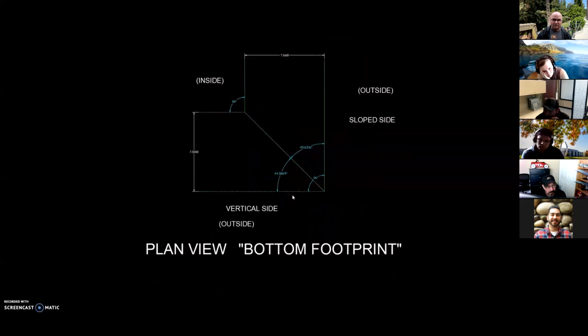With the bottom footprint done, from where we got the compound miter angles, now we're going to make use of this and start working toward getting the compound tilt. Needless to say, a footprint in this case is a horizontal plane cutting through the corner.